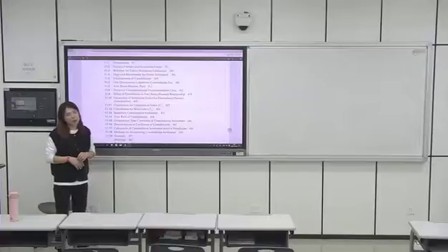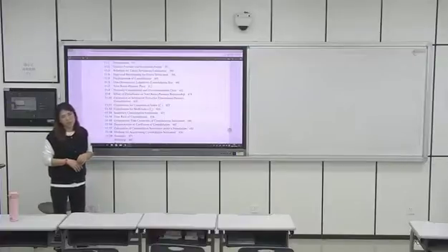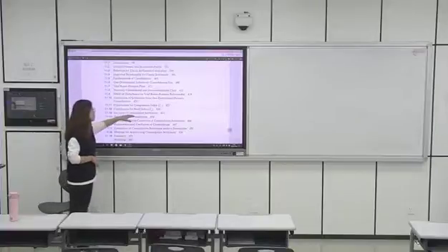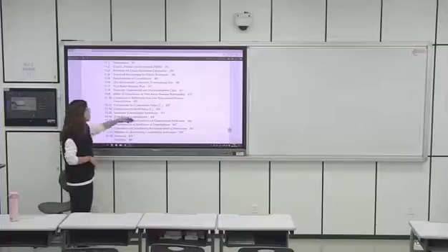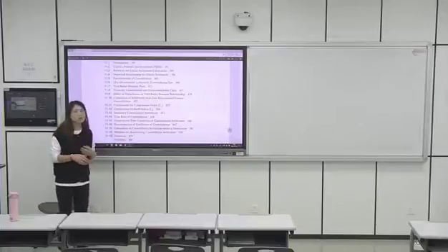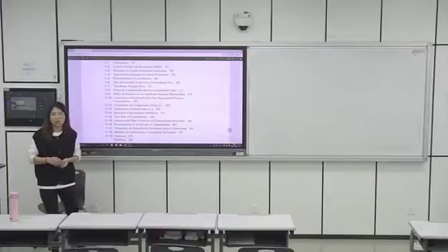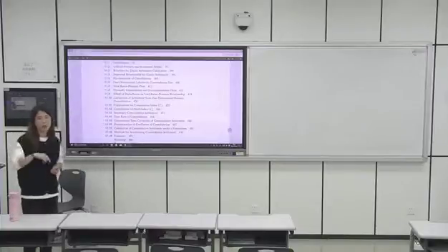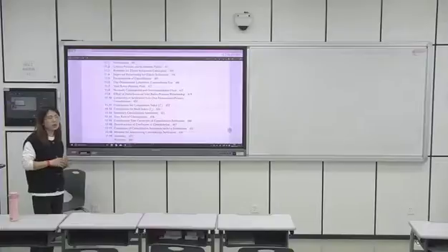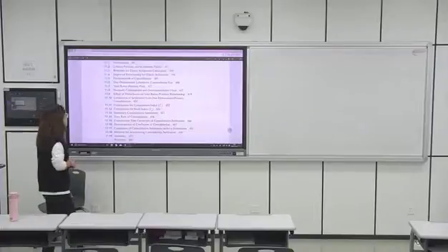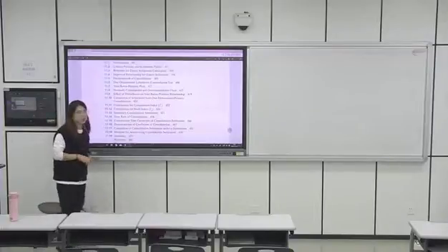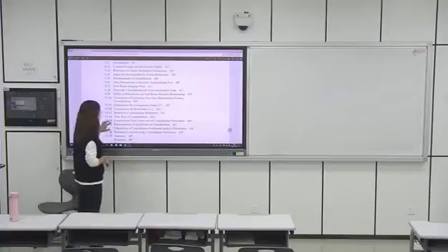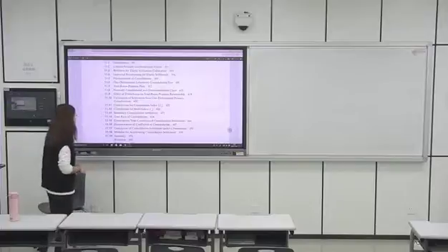Here we actually introduced two important equations to calculate settlement, right? And later we explained what is secondary consolidation and what is secondary consolidation settlement and how to calculate it. We defined a secondary consolidation coefficient C alpha, remember? And how to use C alpha to calculate the secondary consolidation settlement. We introduced that. And later all the others, we didn't talk about that.